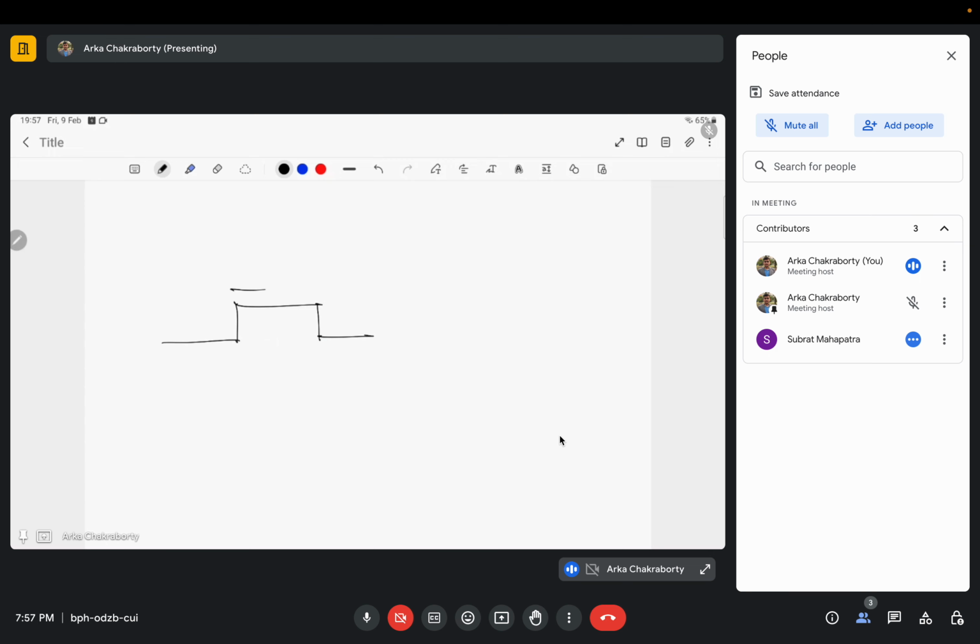I am very much excited about it because I work in the field of memories, so that's why I am telling you with great excitement. There are two oxides here. One is called the floating oxide, and another is called the control oxide. When we apply high voltage, what happens? The electrons present here get tunneled, start tunneling, and electrons